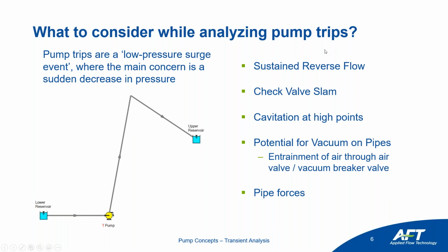And again, let's look for a few of these things. So we'll look at sustained reverse flow. We'll see what happens when we add a check valve that's not properly sized. We'll cause cavitation at a high point. And then again, these two, because they're much more complex, we won't cover them, but something that you should be considering as you look at your own systems.